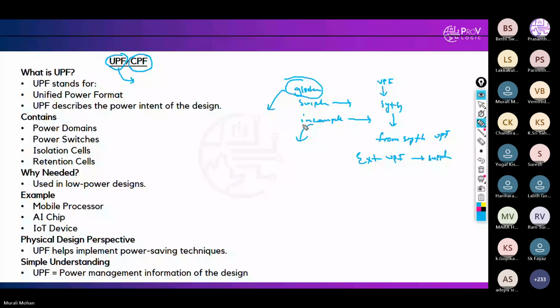UPF stands for unified power format, and it describes the power intent, like how the power is supposed to be distributed to my design. We already discussed this: whether it is one voltage, or the entire design is supposed to work with the same voltage, or what will be decided. These are a few things we write and provide through this UPF.